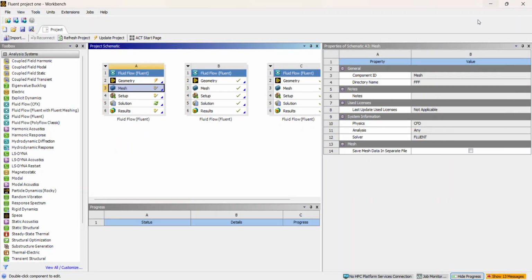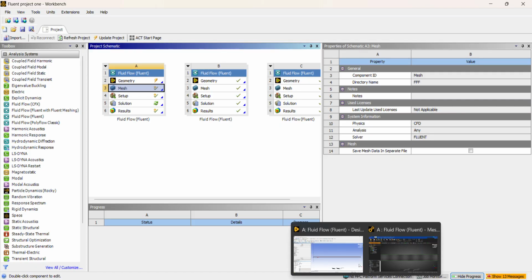And then after that, you go to setup. Just a note, I'll mention this later, but the only difference between this and the Couette and Poisson flow will be the length and the height. Everything else is exactly the same except for the length and height of my box. For Couette and the hybrid, it'll be 250 times 5 millimeters versus 500 times 10.